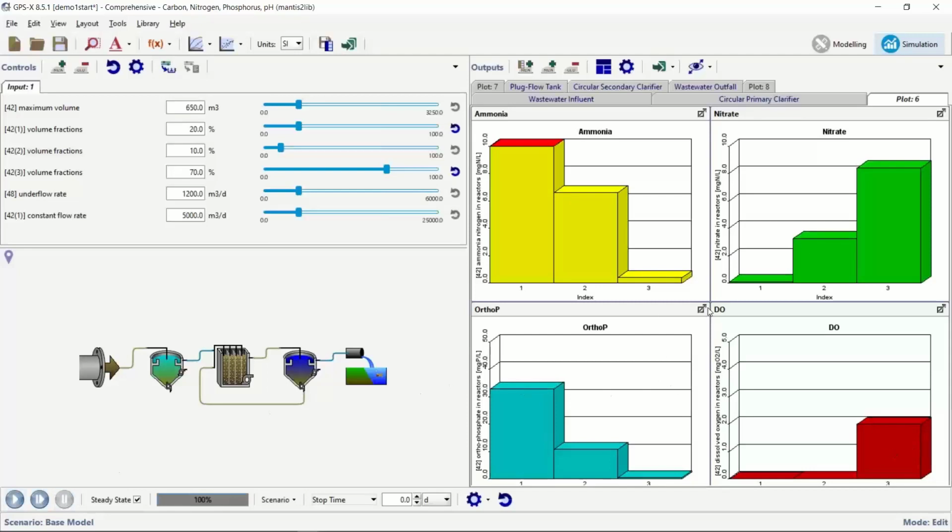So, okay, not a massive amount of change. We're still okay here, but that has improved our P, right? It was 1.1 something before, now it's 0.5. So that was a fairly good improvement. So let's see if we can also improve the denitrification here. This is 8.4 for our nitrate. So if we make this zone bigger, our anoxic zone, then that might help. So let's steal another 10% off of the aerobic zone. So now it's 20, 20, 60. And run that again. And you can see that really actually did improve a lot.